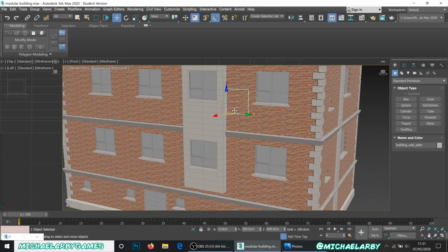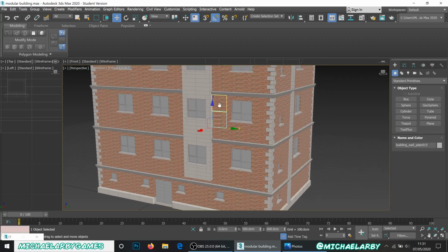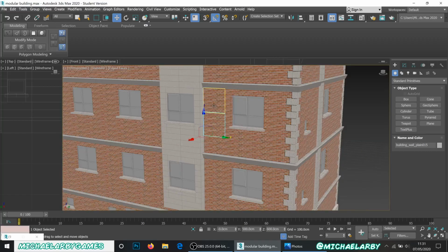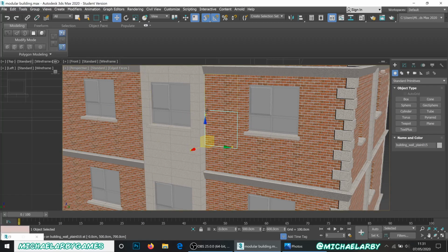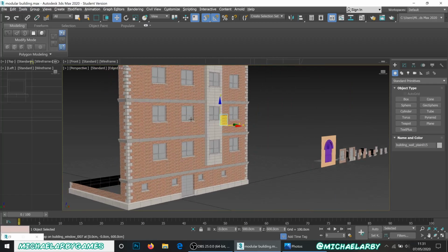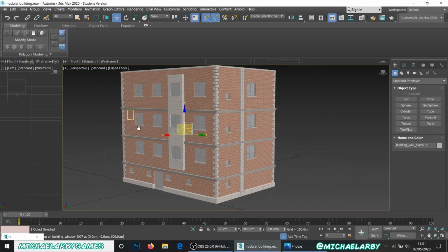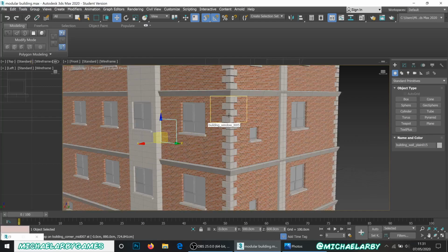And you can see here how it works. Rather than me modeling this entire building, I just model small pieces of it and then copy paste those pieces. I'll use my snaps tool just to snap one corner to one corner, make sure they all line up together. But that's really all there is to it. It's actually a very simple concept. Now, you can see I haven't even finished the building here. I've only done this near side. But you can see, in theory, it's actually quite simple what's going on here. We just take our individual pieces, like those individual Lego bricks, and we just copy them and repeat them as many times as we want.